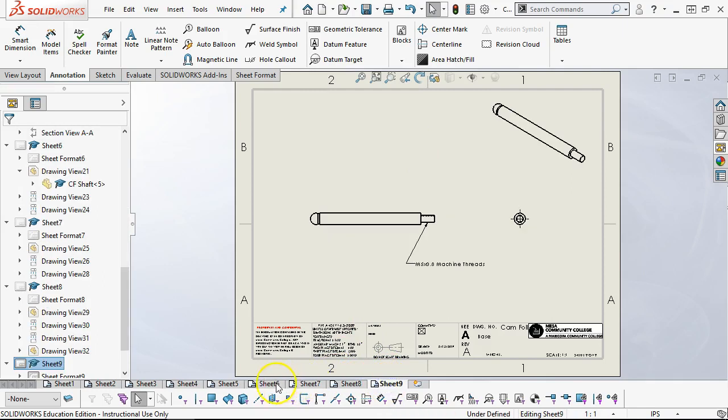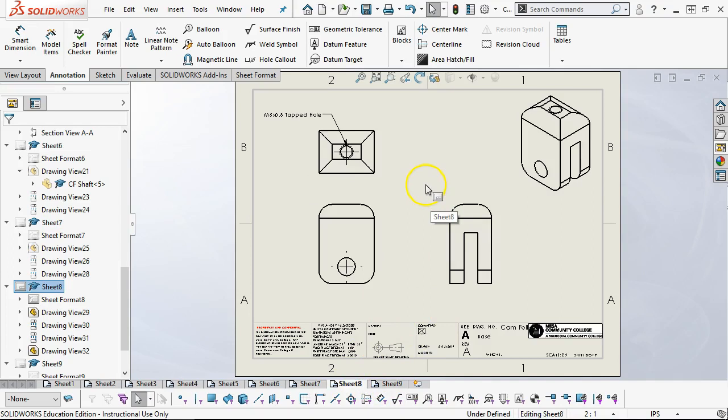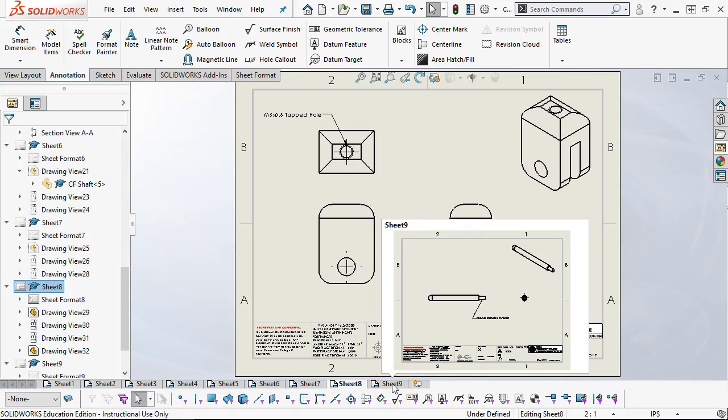All right, so let's see, what were the other ones? Then the cam was thinking that this would be a surface of profile, even though it is circular. If we were to modify this cam, then we would have additional geometry and positional tolerance for the keyway. Pretty much the pins to press through, so the through hole through both faces will need to have alignment.